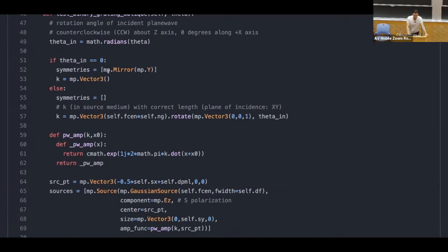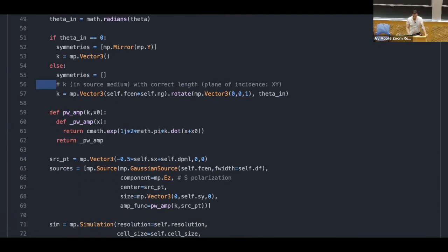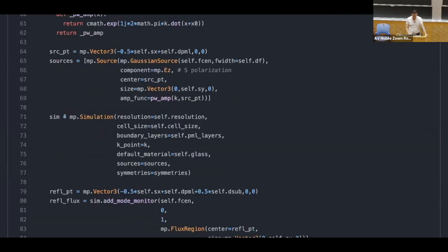But before we get to the grating calculation, we have to do a reference calculation where we compute the power from just the source. The very first calculation we do is we define a simulation object with just the default material that's glass everywhere, with our source, with our power monitor. We do the time stepping. We compute the power generated by just the source, because we're going to need this when we normalize by the power from the grating to get a normalized diffraction efficiency quantity.